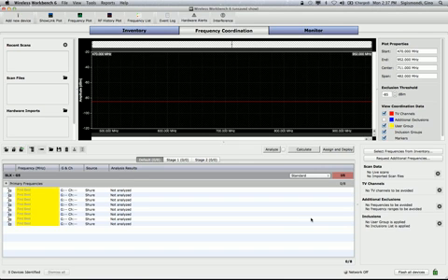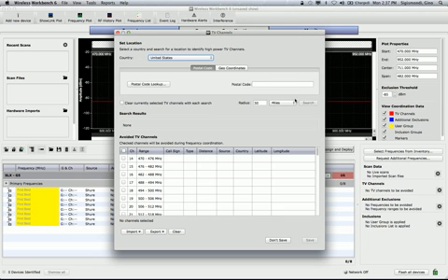And these aren't network devices, and let's assume that I can't acquire any scan data, which we mentioned earlier is definitely the best way to characterize your RF environment. We still, however, want to make sure that we know roughly the RF stuff that's going on where we're going to be operating. So since we don't have scan data, we'll jump down to the TV channels dialog, and we'll click this gear to open up this dialog.